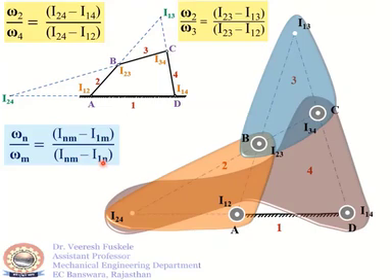As we are seeing the velocity of any instantaneous center, whether it is on link 2 or link 4, or if we are considering I13, whether it may be on link 2 or link 3, we are always finding out the velocity of the instantaneous center with respect to the fixed link, that is taken as 1.